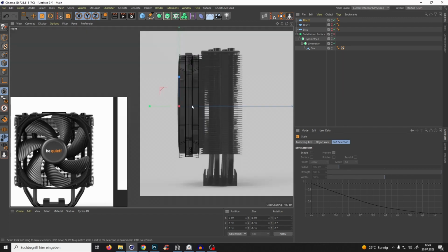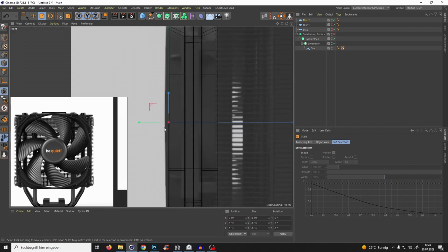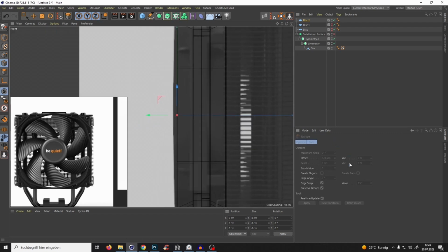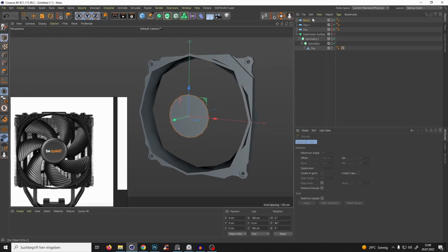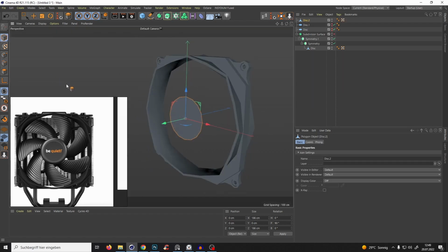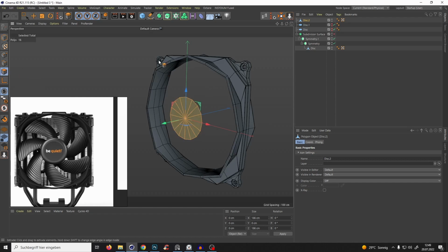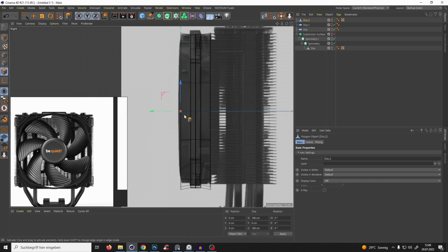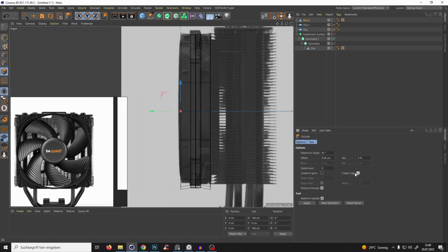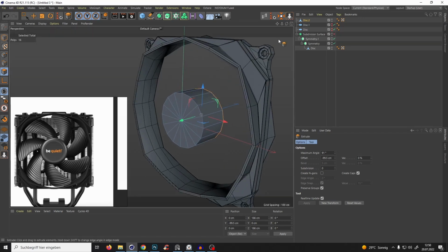And if you go to the right view, it is in the front what we need. First of all, we have to make it editable with C. Polygon mode, select all, go to the right view, and with D for extrude, with creating caps, we extrude it something like that. Doesn't have to go to the end, because I think it's also just bring it to the end. So yeah, we have something like that.